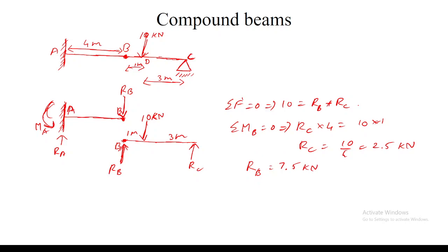So why am I putting the shear force at RB as downward for this member AB? Because point B is balanced, and there are no external forces acting on this hinge. So any reactions acting on point B will be balanced by the two beams. When I take the left hand side beam, I draw it separately here.